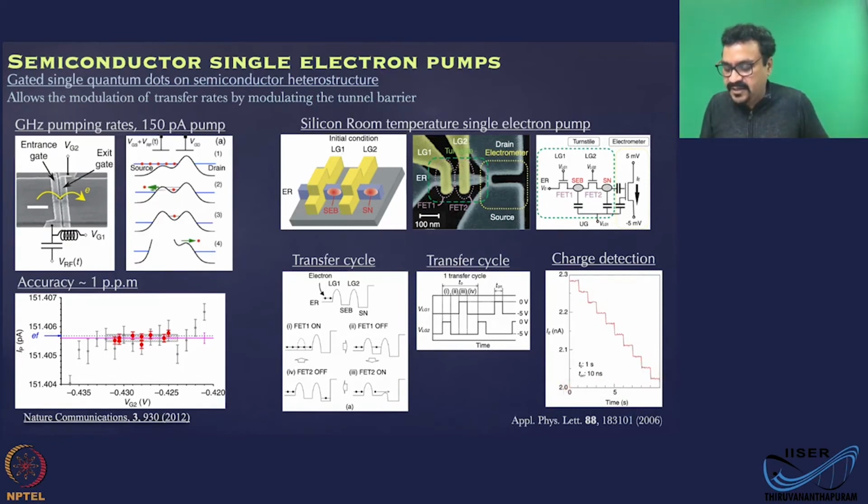When you have more and more electrons collected on it, you have more negative charge built up, and what you are seeing is a reduction in the current in a step-like fashion. So what this experiment is telling you is that you can have electrons tunneling through this in a very periodic manner, and the discrete changes in the island potential are detected by a discrete change in the current through this sensor. This is an electrometer.